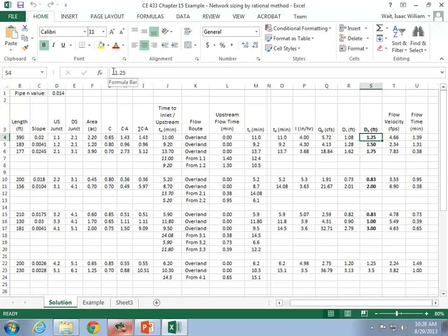the bigger the area, the longer it takes for flow to get there. And so we're designing this for a worst case scenario. If you've got a small area that takes less time to concentrate, then you have to worry about a big intensity. But if you've got a large area, you're contending with the area as being the primary driver for the runoff, but you've got a lower rainfall intensity because of the longer time of concentration. So that's all I can give you for now to explain it.